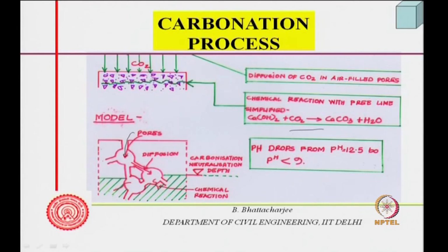and as it penetrates, it must be a moist pore, there must be moisture here. In absence of moisture, the reaction will not proceed, because it occurs in solution phase, carbonic acid will not form. So, carbon dioxide plus water is necessary, and therefore, water has to be there. So, it comes through the pores, water has to be there, and as all alkaline material up to this zone